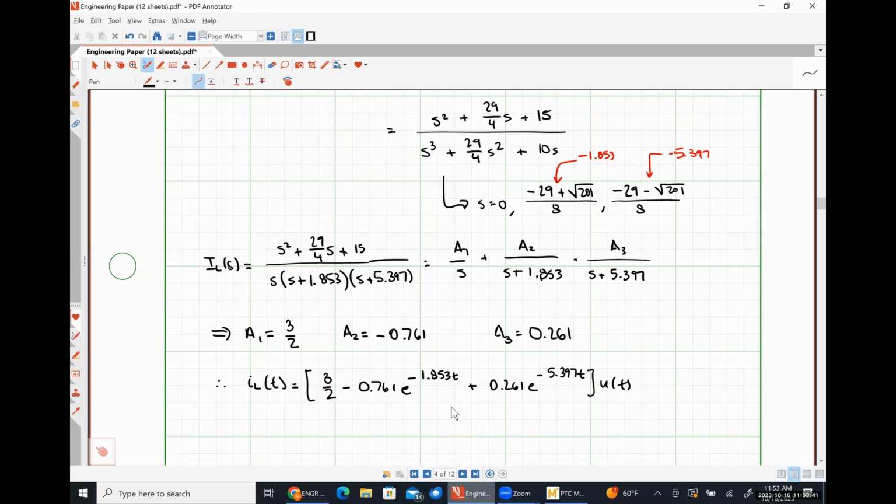So if there were a positive sign here, no, only going to be conjugates if the inside of this thing is a negative number. So if we're taking the square root of a negative number, that means we're going to have complex conjugate poles. Because using the good old quadratic function from 8th grade math, because this was a positive value, it's just an ugly real number and a second ugly real number. If what's under the radical is negative, then we're going to have a complex number as our thing.